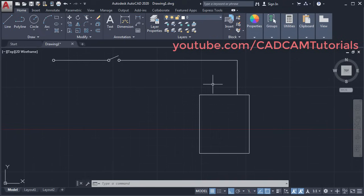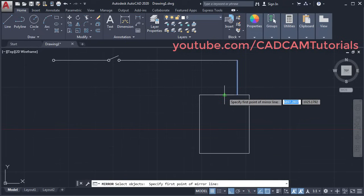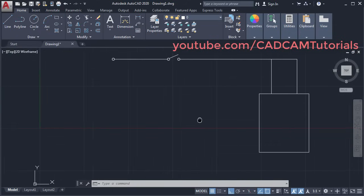We can mirror this line here. So it will come exactly opposite on this side. Click on mirror. Select this line, enter, then specify first point of mirror line. So our mirror line will be in the center. Therefore we will take this midpoint. Click there, take your cursor below, ensure that your line is straight and click, and press enter. So here these two lines are created.